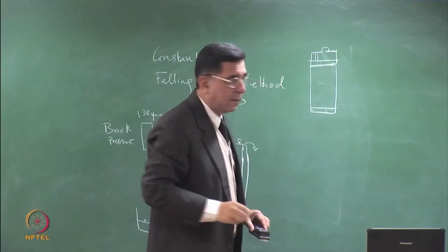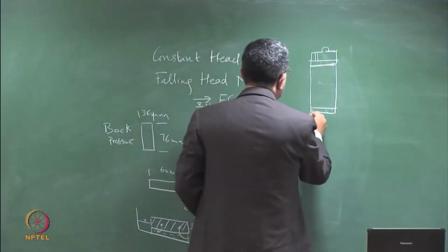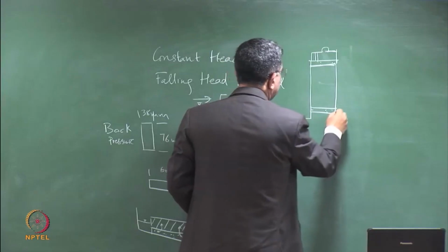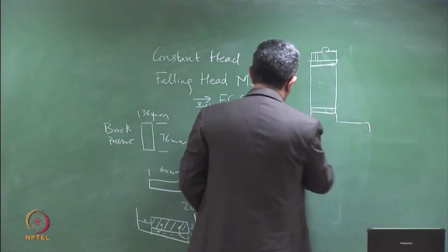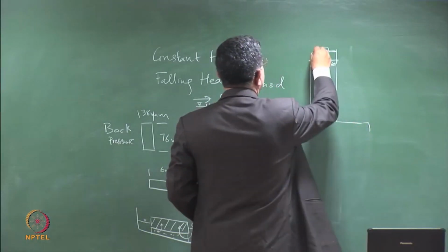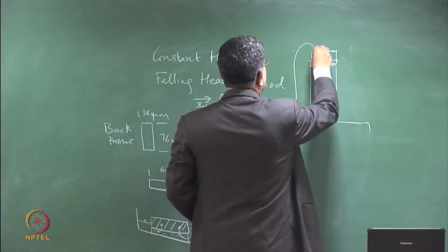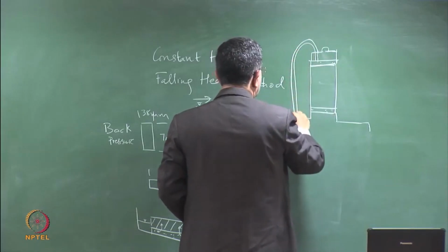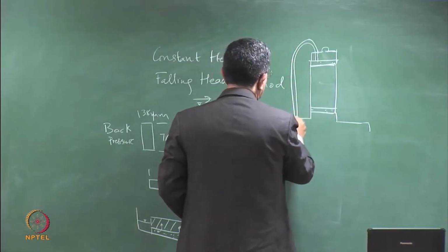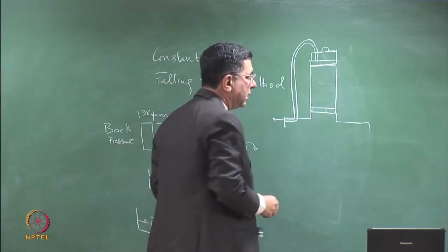Okay? And this is attached to the pedestal of the triaxial cell, you recall that? And this hole can also have a pipe which is attached to the base pedestal. And this can come out from one of the 4 valves at the bottom.